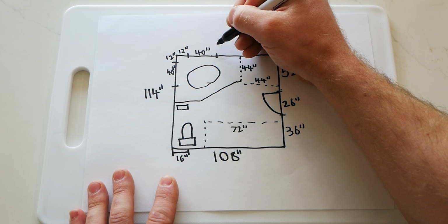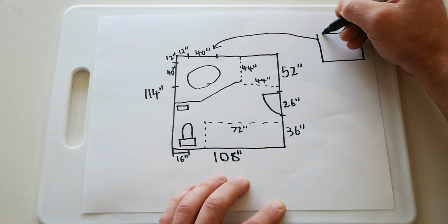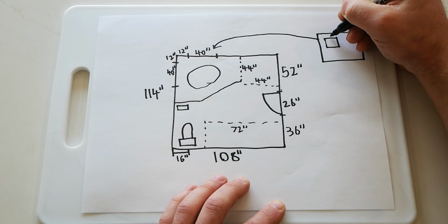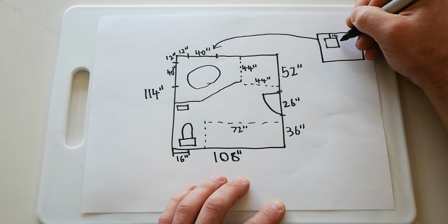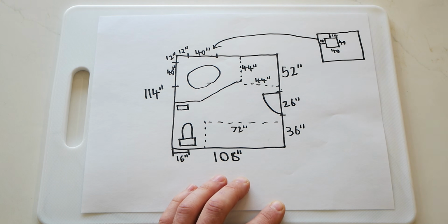And finally, I also do find it useful to just get the sort of height for those windows. So I'll just take a measurement from the ceiling down to the top of the window and then the overall height of that window too. So I might just make a quick little secondary drawing to reference that for later, as that can really affect the layout and design decisions that we are going to be making for this bathroom.